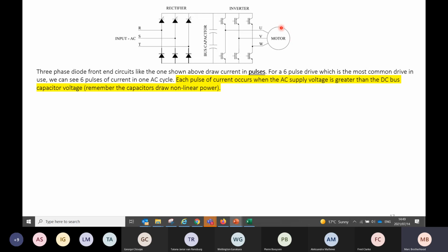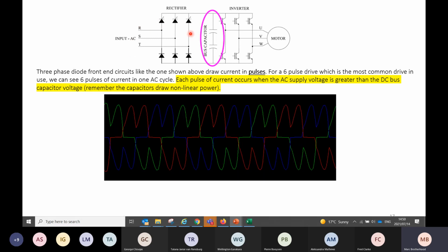If this is the motor, now my inverter compressor will start to turn. It takes its power not from the electricity, it takes its power from these capacitors. So if this capacitor only supplies it, say, 30 volts to start running, then this capacitor is only going to take 30 volts of my waveform coming in. And that's going to be a problem. Because it only draws in a discontinuous manner, and when it needs power, this is what it starts doing in reality to my waveform.